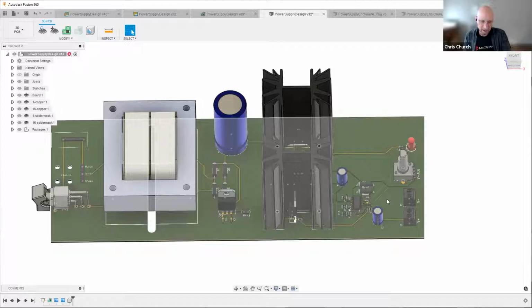So if we had a lot of SMT here, we'd put all our test points on one side preferably. It makes it real easy. We only have to develop one fixture. It's very cost effective. Likewise with flying probe, we can use the actual pins on components like these guys here, but it's often unreliable. So we're still going to want to add some test points for those devices.